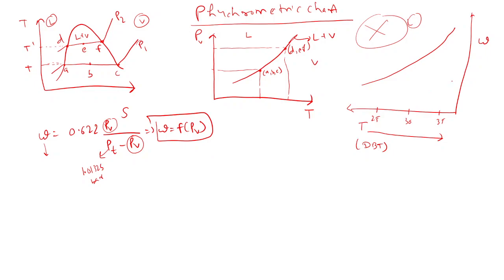If you know omega, and if you know T directly, like temperature 28 degrees Celsius, just draw one line this way. And if you know omega is some value, draw this line this way. Whatever point this is, this is the initial condition of air. So we can get all properties from here. We'll see later what properties we can get.